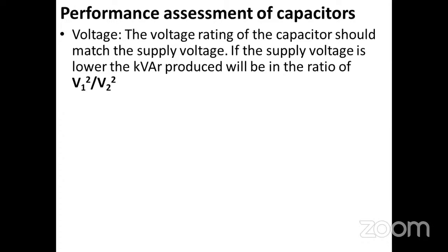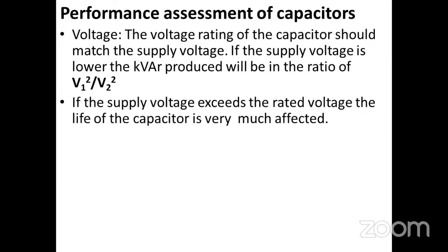The voltage rating of the capacitor should match the supply voltage. This is one important point, sir. If the supply voltage exceeds the rated voltage, the life of the capacitor is very much affected.